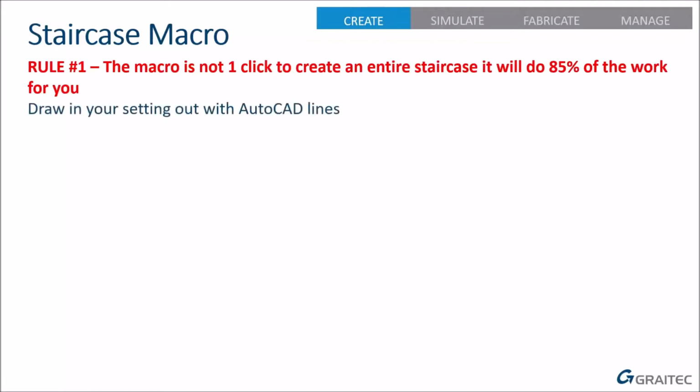The very first thing you need to do is to put in your set out points correctly. So we strongly recommend, although it's 3D modeling in Advanced Steel, you basically just use some simple 2D AutoCAD lines to draw in some construction lines and some construction points. And if you get these right, everything else drops into place. If you get these wrong, you'll never get anything else right. So the 2 or 3 minutes spent doing this is well worth investing.